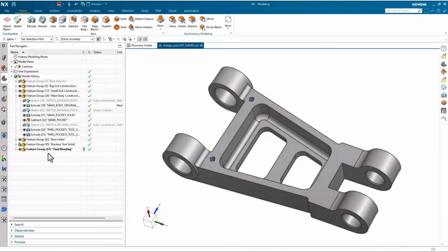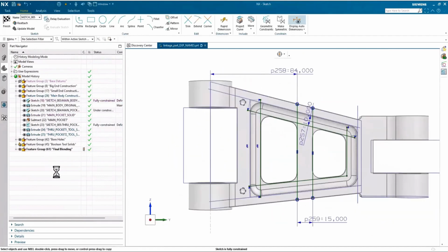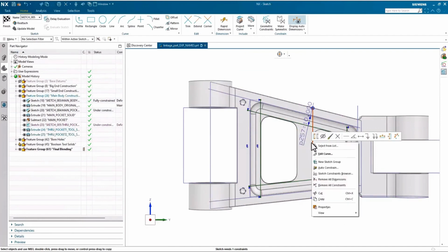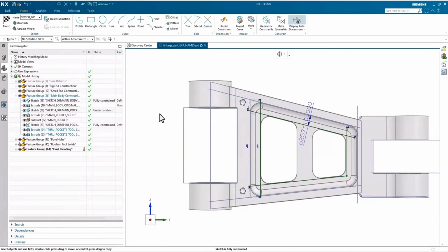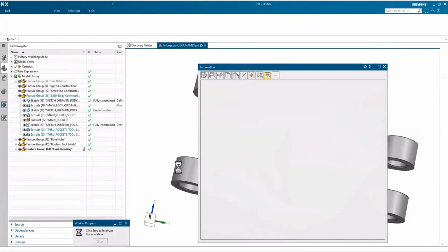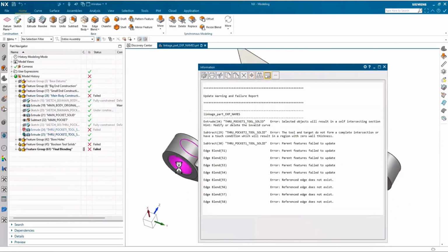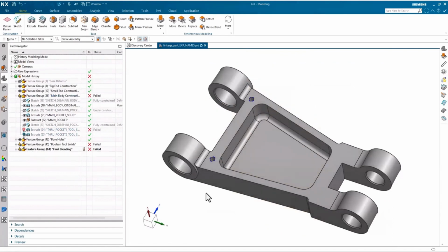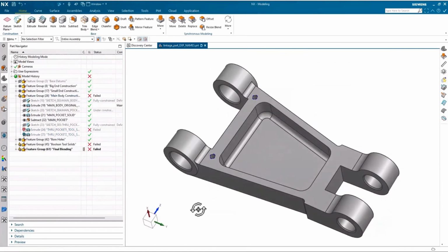Now if we look in 2306, when you go in and edit that sketch, you can see it's using the old sketch task environment. It still has all the ways that we did that, and you can work from those to remove geometry. The main thing was if you were changing the actual curve geometry in the sketch, that's the main reason to be able to do that. And so that just shows you a way that, in the new sketch, here's how you can work with those and move forward.